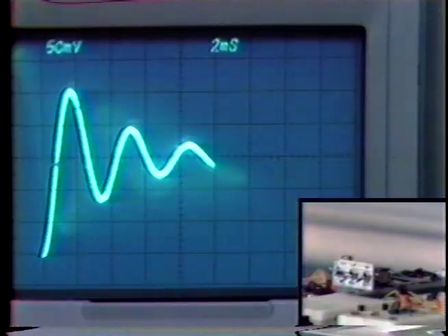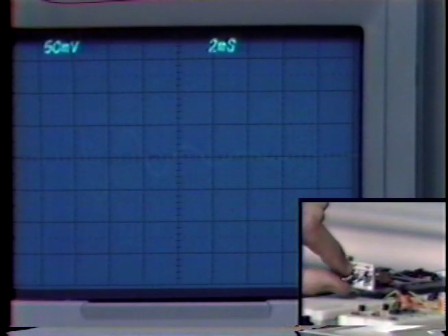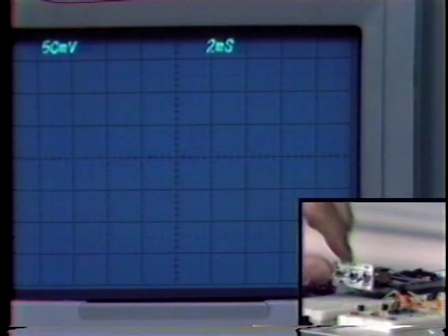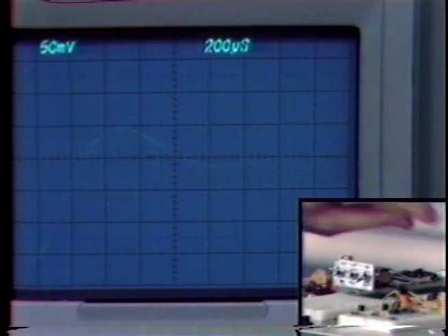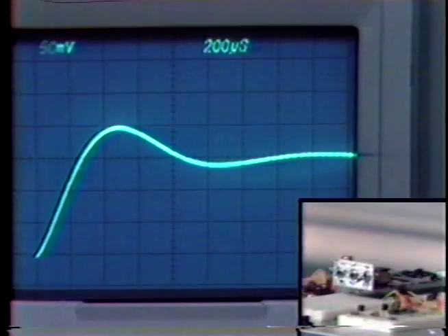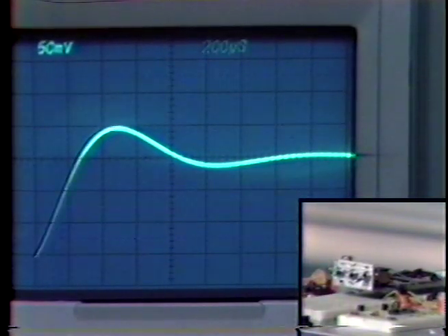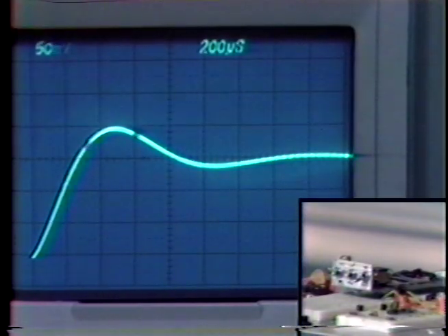And beyond this, we begin to lose things quite dramatically. But again, at this point, the 1 over S compensation had just completely lost. In fact, we had a lot of trouble with 1 over S compensation when we located the pole at 1 kilohertz. Here the system is very well behaved with this very simple compensating network when the pole's at 1 kilohertz.